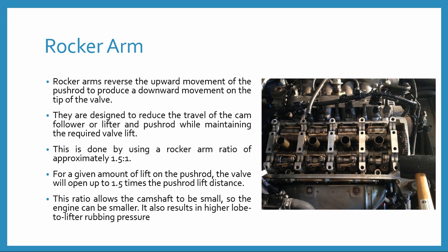The rocker arm basically reverses the upward movement of the push rod to produce a downward movement on the tip of the valve, and they are basically designed to reduce the travel of the cam follower or the lifter and push rod while maintaining the required valve lift. So this is the base picture, and this one is the picture of the rocker arm.